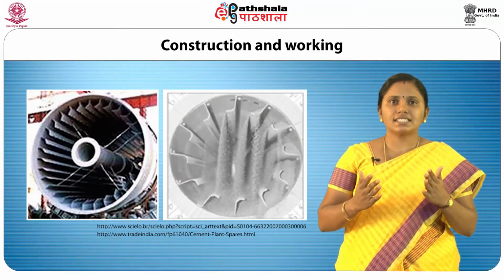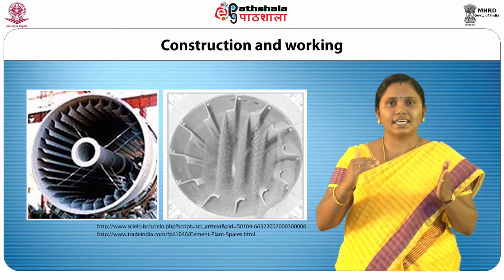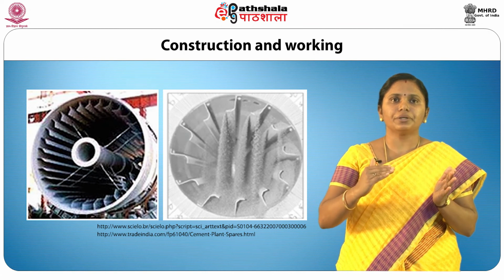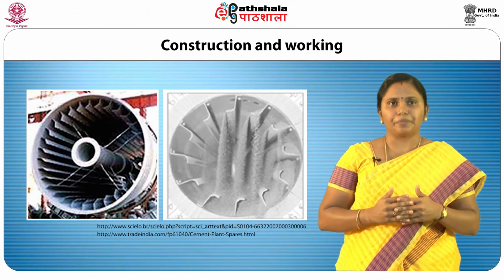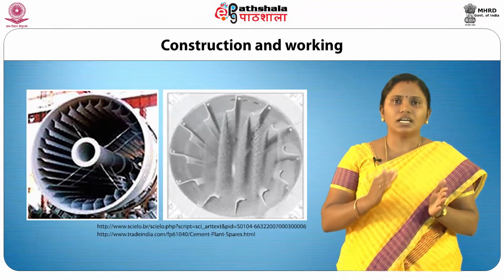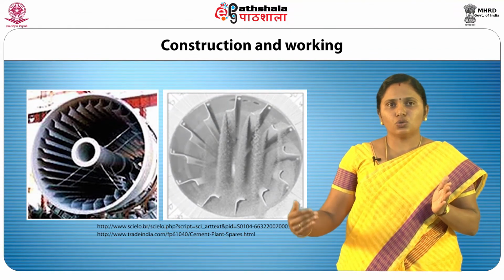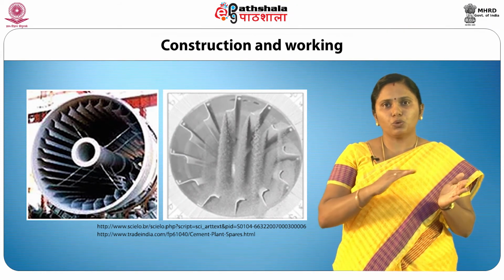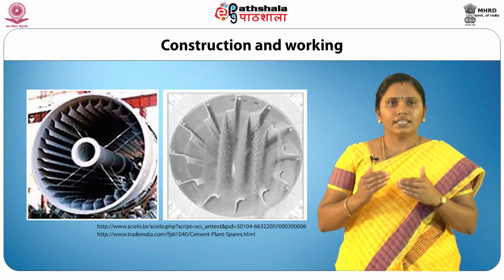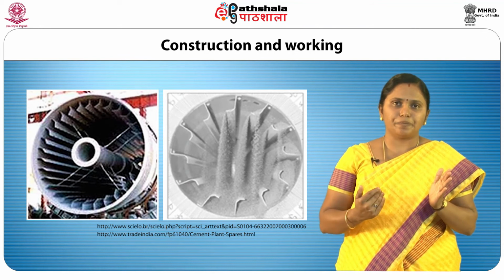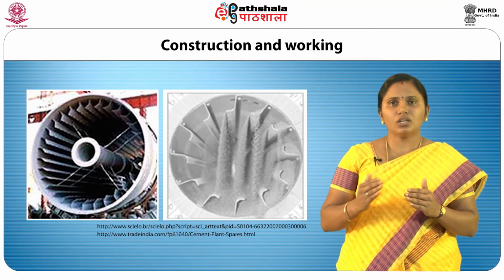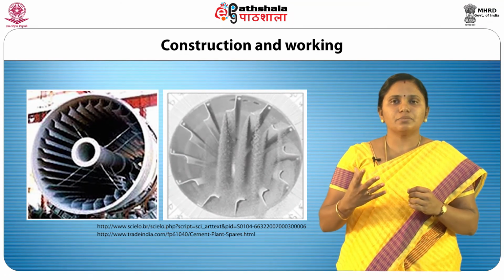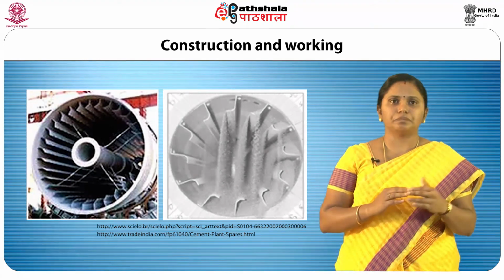The cylinder has internal flights or cascades that direct the movement of the product and ensure good mixing and rapid drying. Usually, the solids are discharged at the outlet through a screw conveyor. The dryer drum rotates on drum supporting rolls. The hot air can be blown from the discharge end. In some arrangements, the hot air is sucked from the upper end. Here, the whole dryer is maintained under slight vacuum.